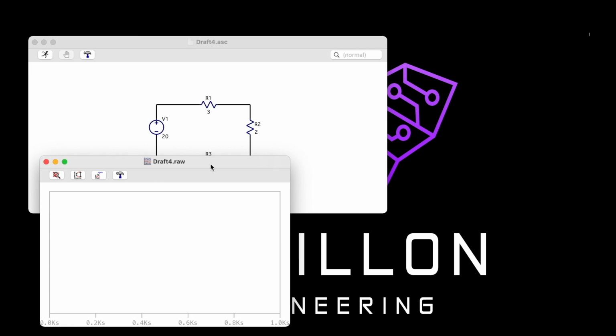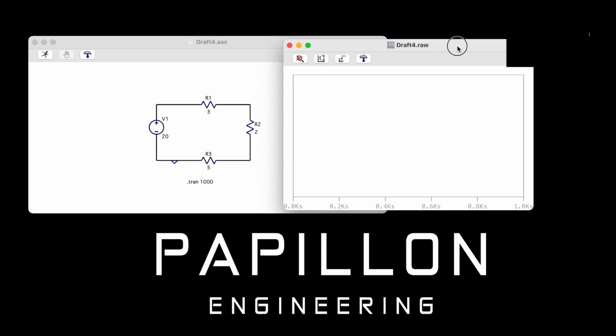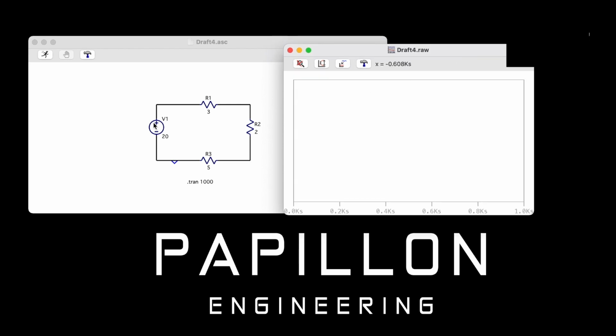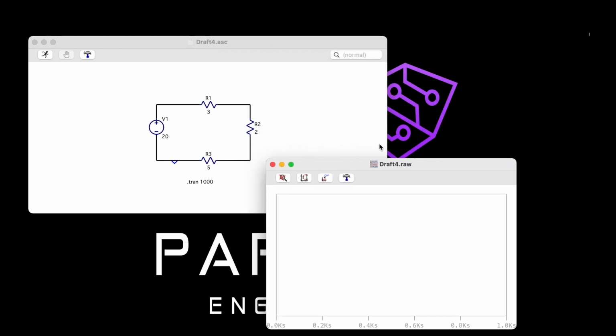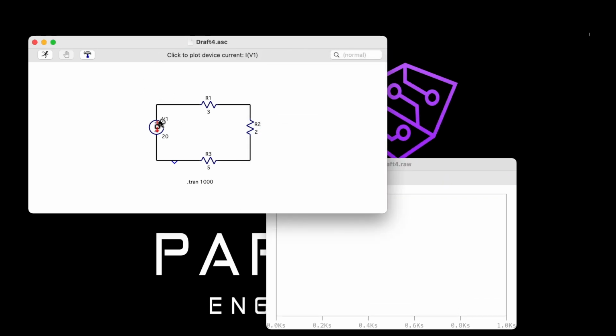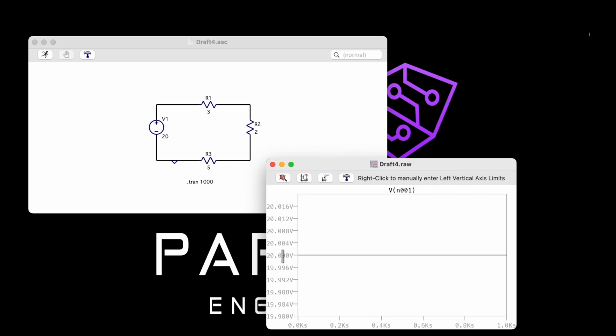Okay. So now that I have that, I'm going to run it, and I can actually see the results on my schematic, kind of like an oscilloscope type setting. Now I can look at voltages and currents of all of my components. If I hover my mouse over each part, that's actually a current meter that you're seeing now. If I hover outside of my components, you'll notice that it goes to red. Those are actually the prongs that we use for our voltmeters, right? And it will then tell you the voltages that are associated with it.